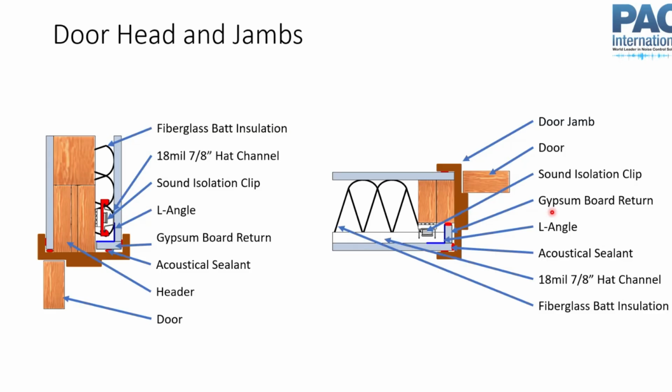But if you've got an apartment building that overlooks the highway, and you know that highway noise is going to be an issue in the apartments, and so you've gone to the effort and the expense of specifying, selecting higher performing windows and maybe shrinking the size of those windows down as much as possible while you still let in a lot of light and have all the benefits of the natural light. You've done things to minimize the acoustical weak link of the windows. Well, then it very well may make sense to improve the acoustical performance of your wall, put sound isolation in that wall. And then you need to figure out the detail between your sound isolation in the wall and that door or window.